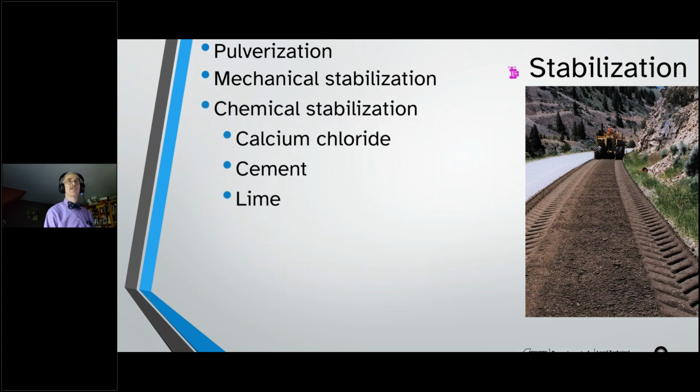You could be doing chemical stabilization. Cement binds the actual fines. It actually cements them together to reduce the fines content. Lime works by hydrating with what's in your mixture. You can use fly ash with the lime to actually bind everything up together. You could bring lime in if you've got enough clay content to work with that, depending where you are in your area. You don't see a lot of lime here in New York, for instance, because we don't have a lot of plastic materials, and you really need some plastic materials to work with the lime.